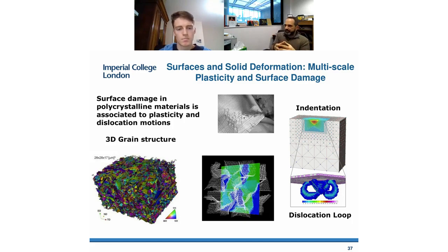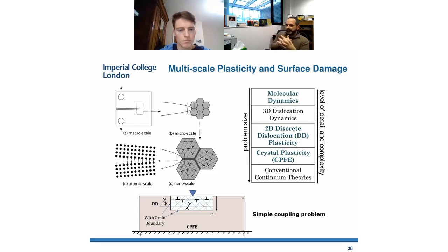So in materials, especially polycrystalline metals or ductile materials, the mechanisms for deformation are particularly important. If you have these materials in a contact scenario, these individual asperity contacts will cause quite a lot of changes within your material. So one branch of what we do with the models is to try to understand how materials evolve in different scenarios. And even in this case, just like we've been saying from the beginning of this presentation, a simulation needs to cover a huge range of scales.